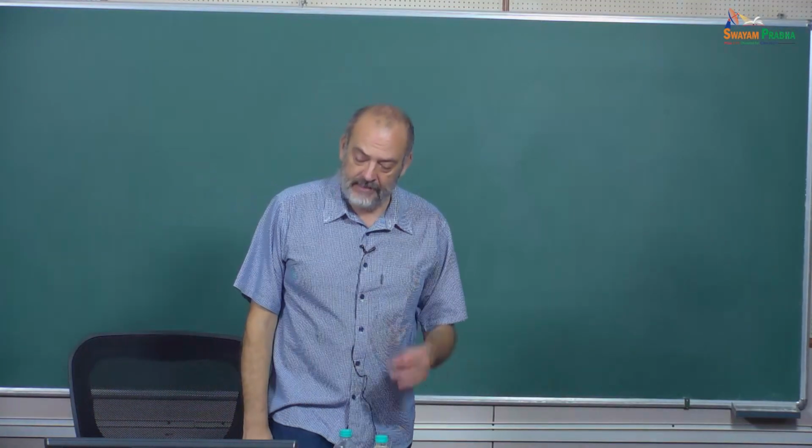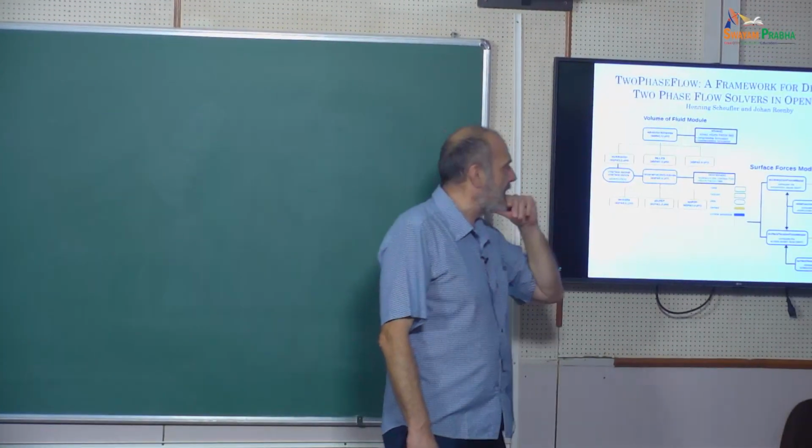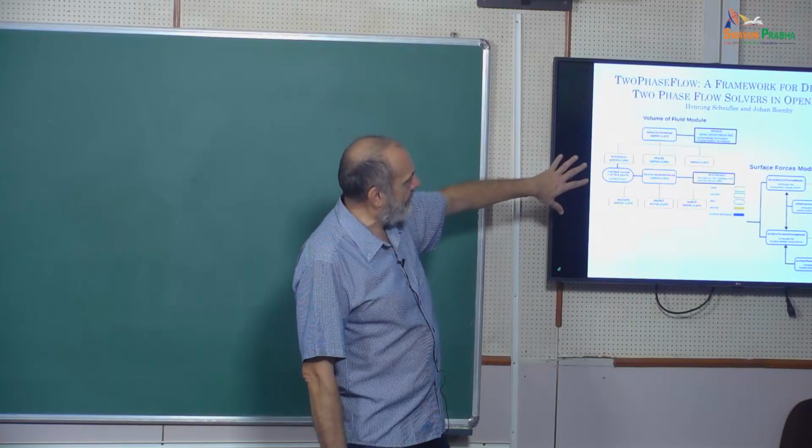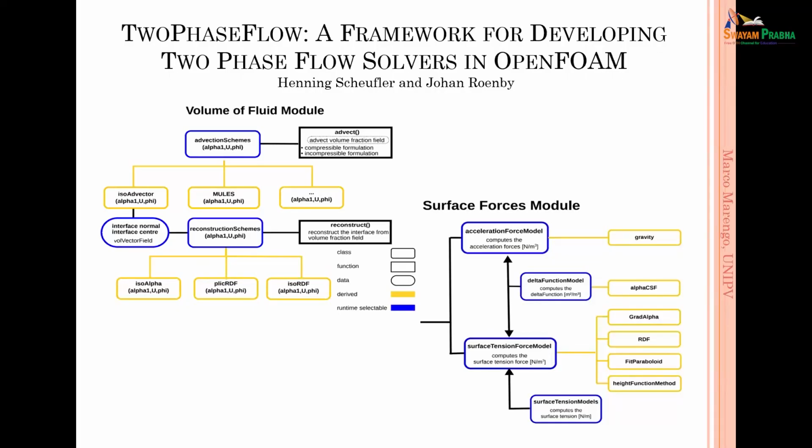So this is a slide that I got yesterday from a student, Raul, that is working on this field, and this is what in OpenFOAM is done about the reconstruction of the surface and the surface forces. And so you have different cases, and honestly, you need to choose the right one. So it's a combination of the advection schemes and the reconstruction schemes. And it's true that there is no general rule. So you need to really try your best combination.